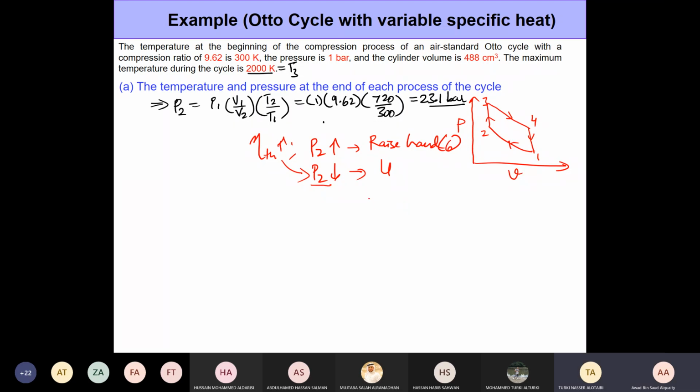We will increase the pressure because it will lead to increasing the temperature, which means increasing the denominator. Since the thermal efficiency is 1 minus TL divided by TH, that's why I said increasing the pressure. Okay, makes sense. That's good.